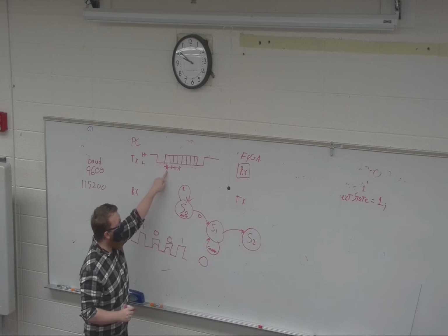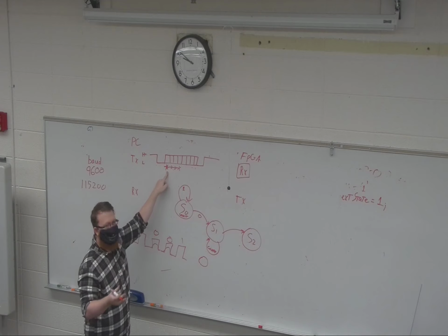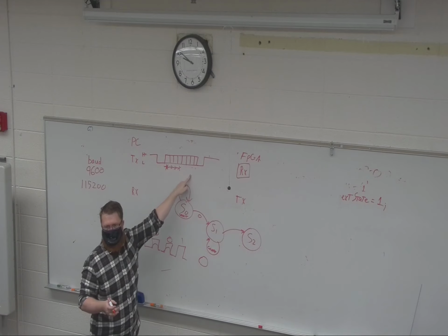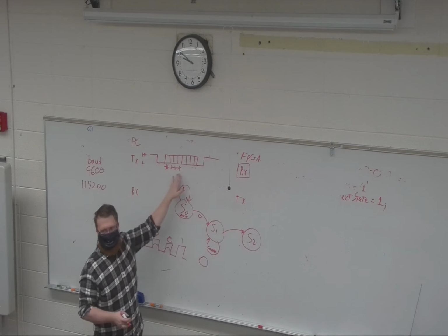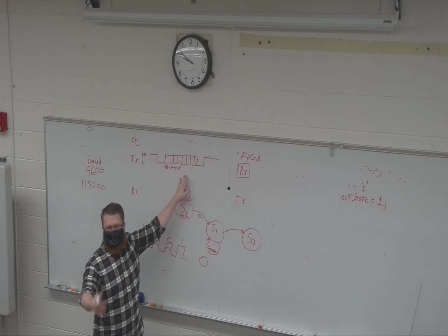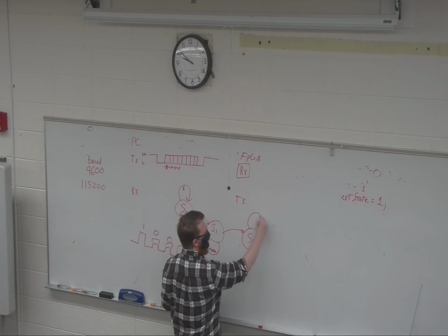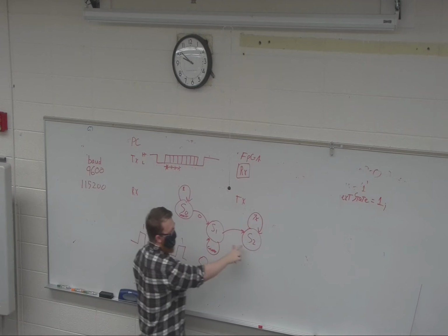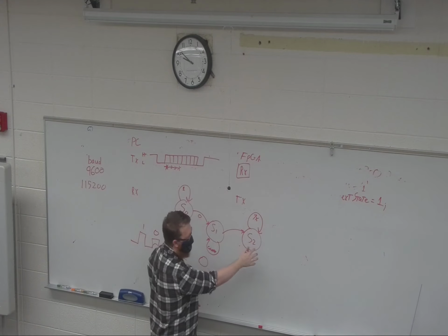And that next state can be done a couple of different ways, right? You could do it the hard way, where you have one state for every single bit. Don't do it that way. State 2 is perfectly capable of just repeating itself while shifting out data, right? So it's actually going to be 7 times because you can store the first bit here. So then 7 times is just going to loop through here, again, just a counter.